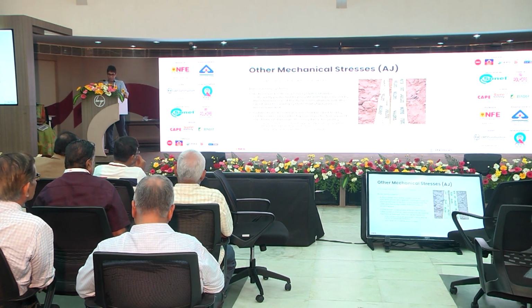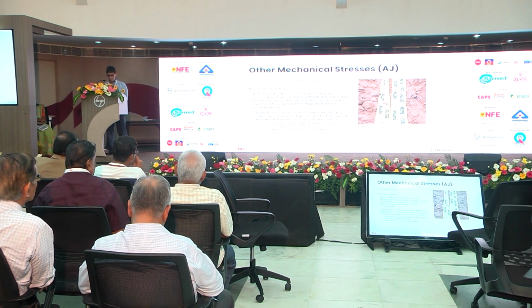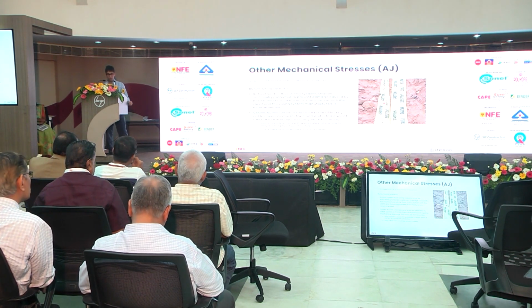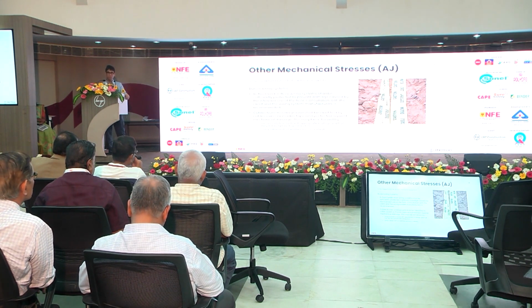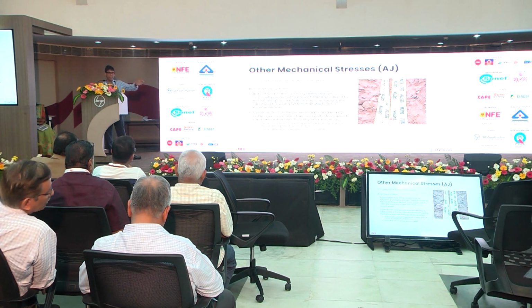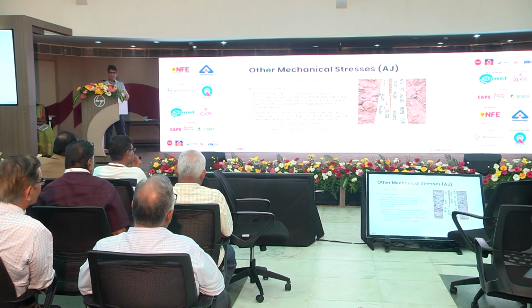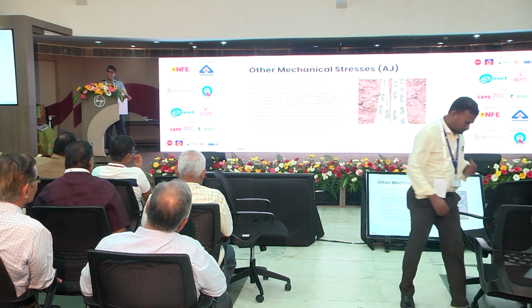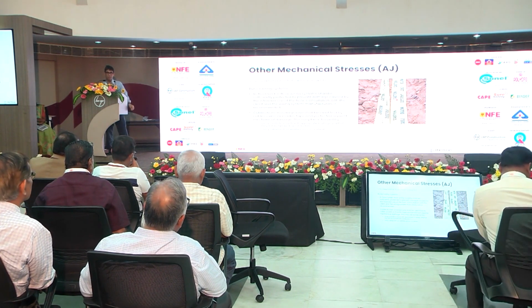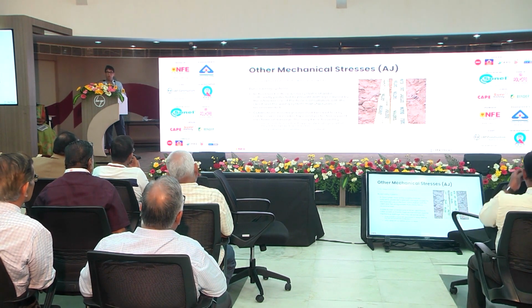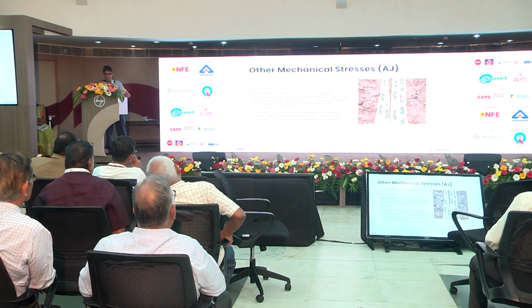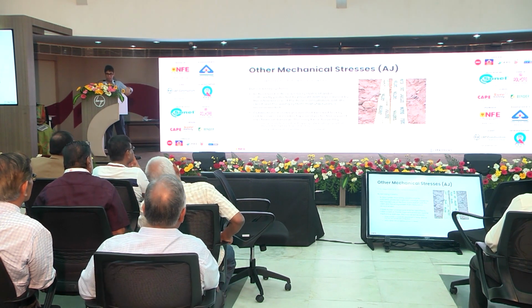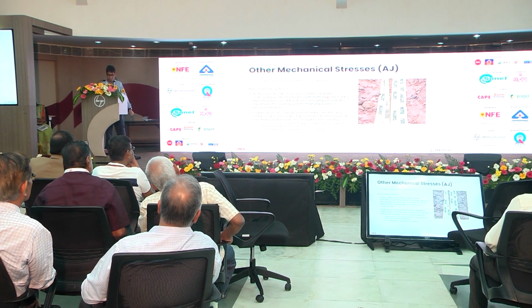Now, if you put wiring through an underground passage, firstly let's talk about soil. So you can see in the image here, you've got cables that are laid underground, and you need to put some sort of tape on top of it and then cover it up. The reason is, let's say there's further civil work or some work by some utility provider. The moment they see this, they will realize, okay, we have cables underneath. Because a lot of times, these people are not going to have access to your drawings, and ideally they should, but if they don't have access to plans that show where the cables are, this is a clear indicator that there's a cable underneath.